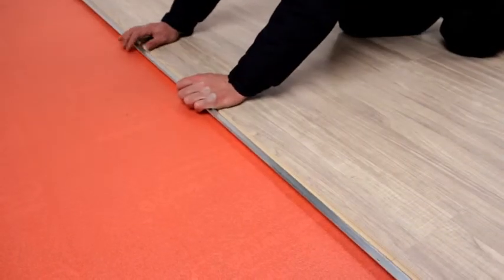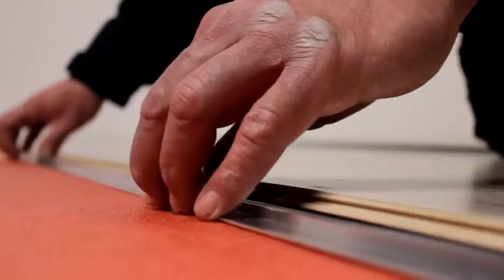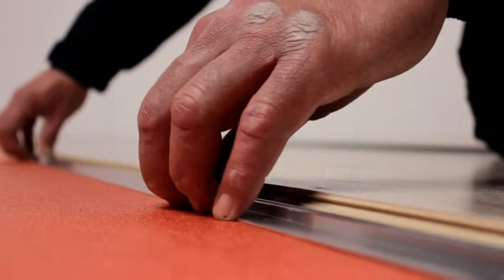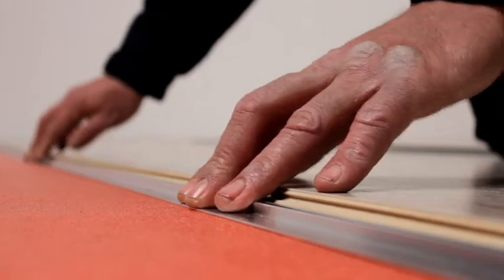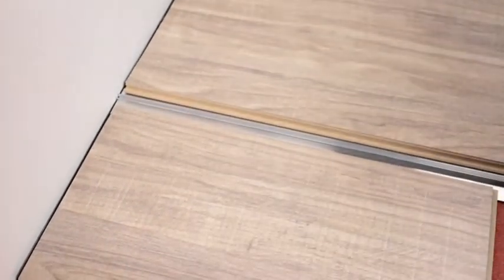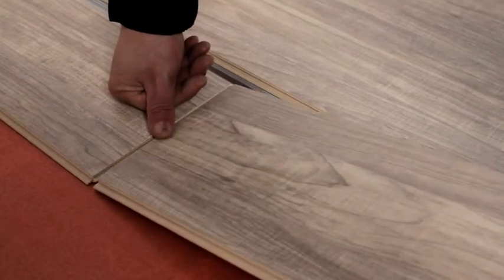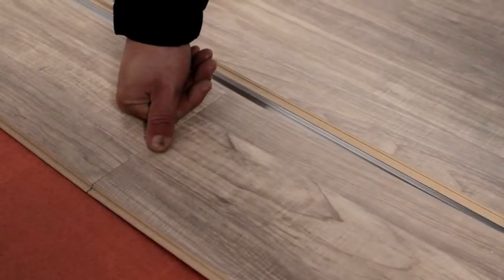It is recommended to avoid laying lengths higher than 6 to 7 meters running, because the expansion allowance from the wall, 1 centimeter, could prove to be not enough. For lengths higher than those above mentioned, it is necessary to insert an expansion joint to avoid the floors rising.